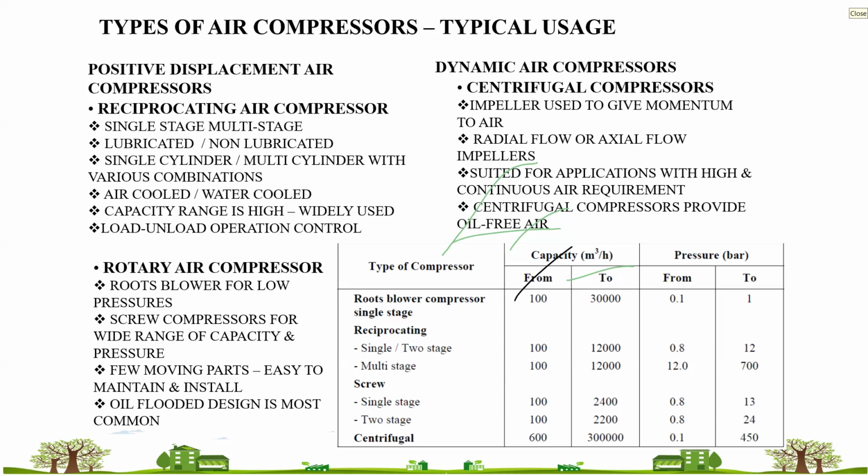The compressor with a pressure ratio of 4 will be doing lower work, and the compressor with a pressure ratio of 7 has to do more work. If you are increasing your air pressure in a single stage compressor, the higher the pressure, the higher your input power will be for the same air delivery requirement.